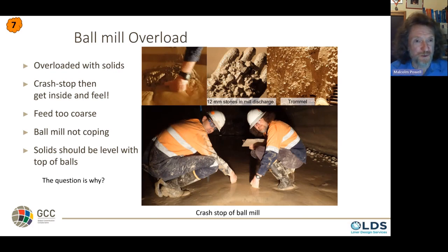Just skipping on to ball mills. Ball mills also overload, but quite differently to SAG mills. I crash stop a mill, which is highly unpopular, but I've done dozens and dozens of them. You just have to make sure the cyclone doesn't drain back into the pump and choke the pump. So you should open the pump if that's a risk.